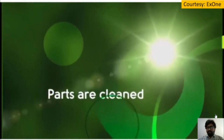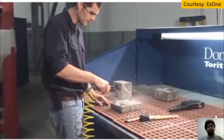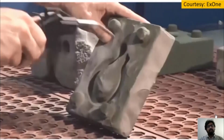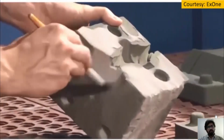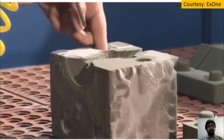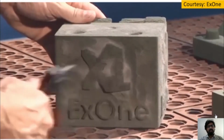Of course, the next step is cleaning the part and removing the sand from each and every portion of the mold. That step is typically done by utilizing a compressed gas and some brushes. Here you can see, as the compressed gas strikes onto the mold, it pushes away the loose powder and leaves the clean mold behind. We need to clean the molds appropriately, because we cannot afford to have any loose sand particles in the cast parts developed later on.